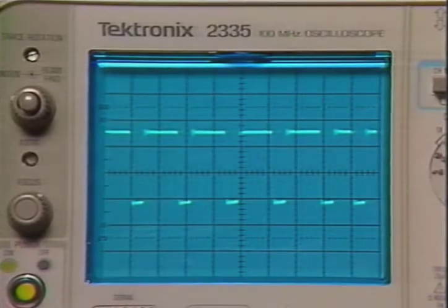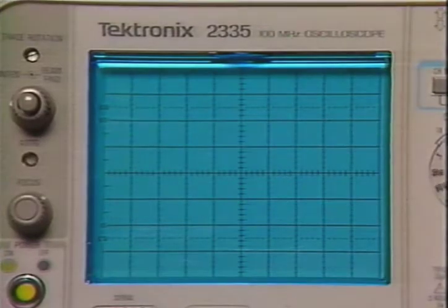The oscilloscope displays information by drawing a graph of the input signal versus time. It does it by moving an electron beam across a phosphor coating on the inside face of a cathode ray tube. The result is a brief glow, tracing the path of the beam. Only an electron beam can be moved quickly, easily, and accurately enough to draw graph lines like these in milliseconds, microseconds, or nanoseconds.